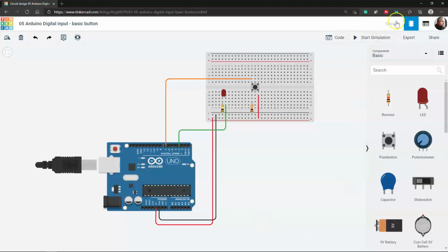Before doing anything else, I'll just show it actually running. And we can see here, hit the button, light goes on, let go of the button, it stops. To make that easier to see, I will change the resistance here again, so I'm lowering it. It has much less resistance, but enough to stop the LED from blowing up. Click run again, and we can see, boom. Press the button, it goes on, release the button, it goes off. I'm pressing it down just by clicking on it, and we have that signal coming in.